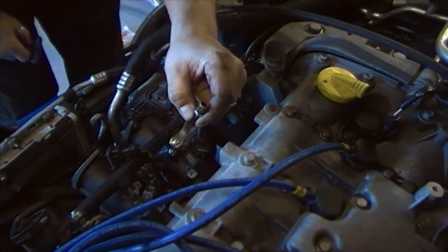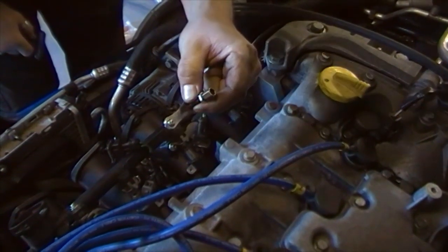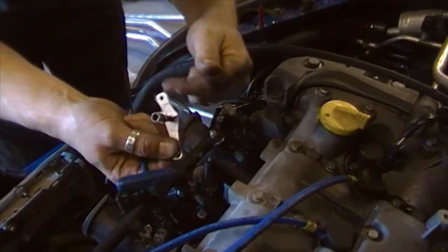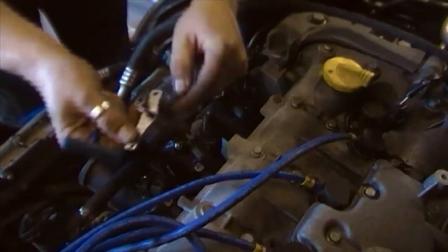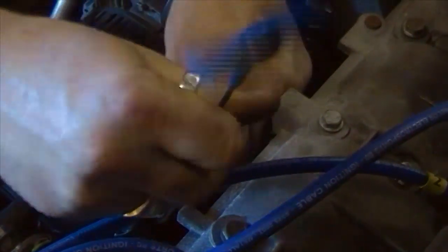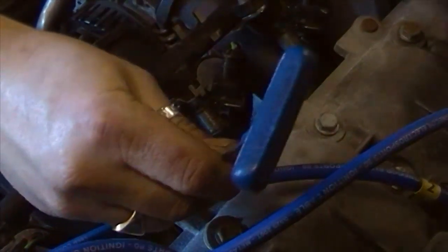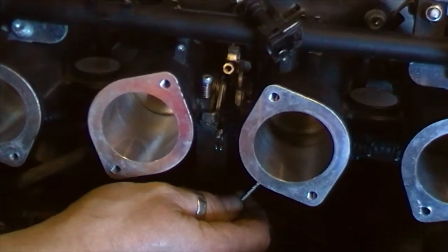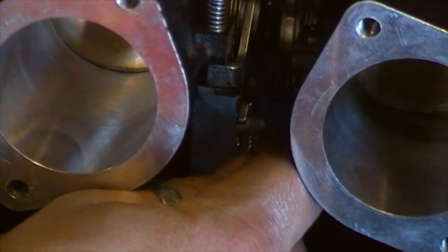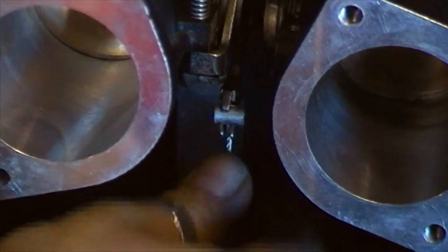Okay, now before we put the inner cable in, we need to put the cable guide on. Now as you can see, this is offset, this side being shorter. This needs to go to the left and line up with the throttle linkage itself. It needs to be lightly nipped up. Okay, the next part is to put the end of the cable here into the throttle linkage itself. So slide this in through the side and then up there.